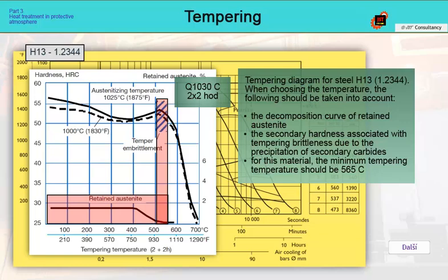The amount of retained austenite shows how much volume of austenite remains in the structure without transformation to martensite. Steel with such a portion of retained austenite will be unstable, because even at room temperature, the retained austenite will tend to transform to martensite by diffusion processes, although this may take days or weeks. However, since martensite has a larger volume than austenite, the steel will change dimensions, which can be a problem with hundredth tolerances, and at the same time, it will be loaded with high internal stresses precisely because of this change in volume.